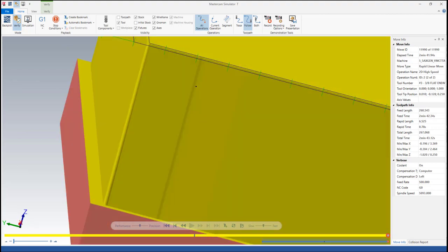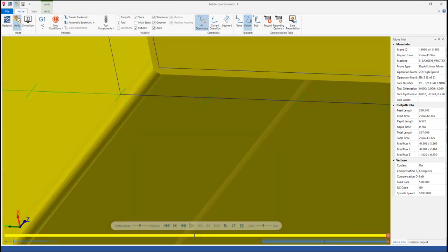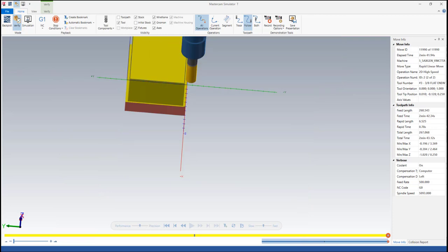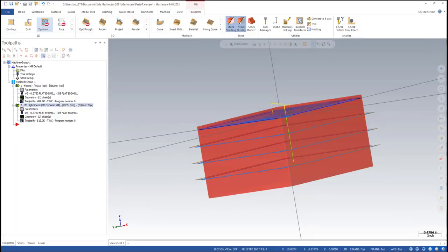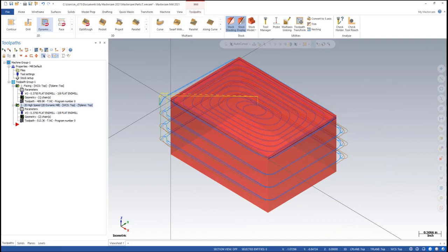you can see these little ridges here are because that goes back to, you don't want to use dynamic motion as a finishing move because it's not perfect. It's not what you actually want it to be. So that's why you want to leave a little bit of stock and then clean it up with a proper contour later. So we'll go back to here and we'll do that last operation, which is just a contour.